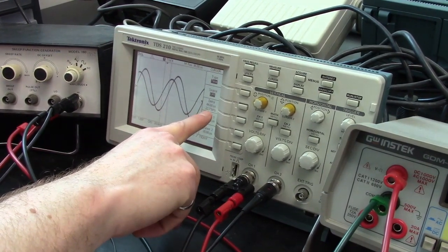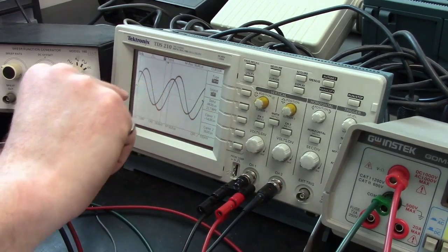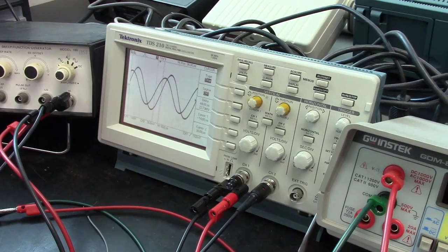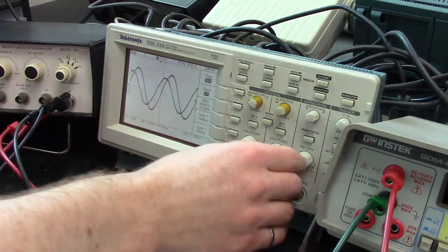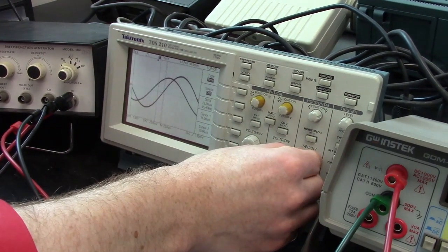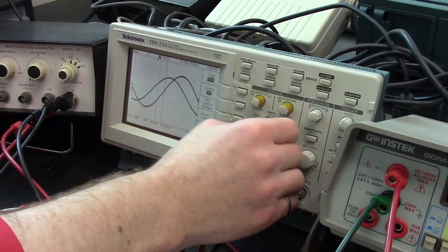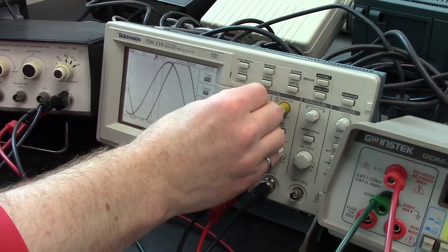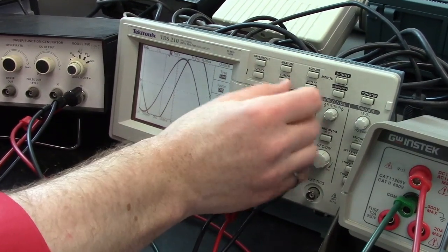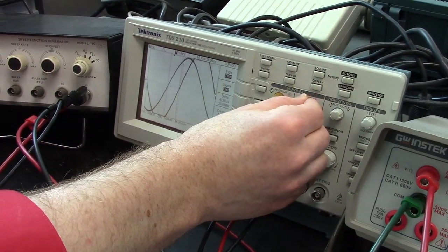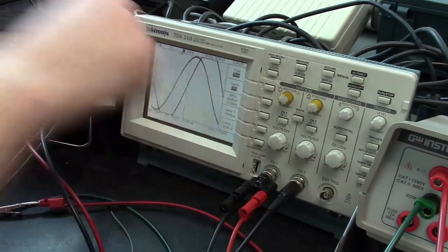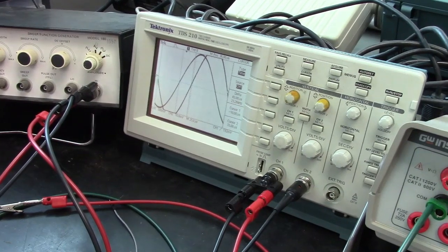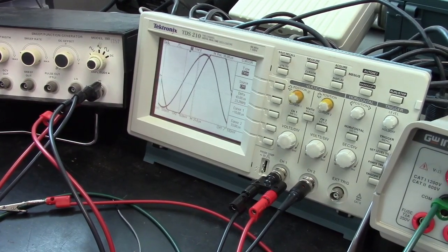So it's saying 44 microseconds right now, and once again we expected about 46 microseconds. So that tells you the phase difference is pretty much what we expected as well. You can get a better measurement by increasing this even more on that scale, maybe turn up the volts per division to see more clearly where they cross the axis, and sort of zooming in on that, we end up with a measurement which is now about 43 microseconds. So those are ways that you can make this measurement a little bit more precise.